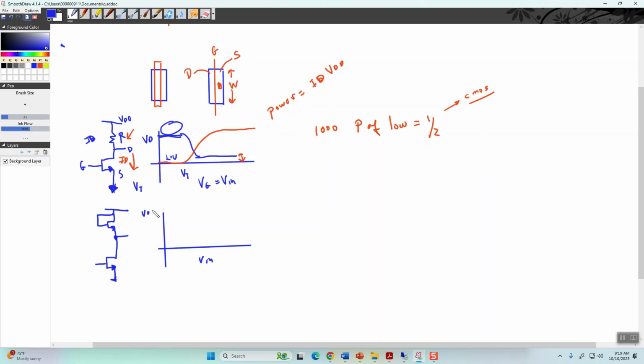Now, what happens is that this can go rail to rail, right? If no current flows, there can be no voltage drop, and so these get connected. Here, however, in order to charge this node to a value, current does need to flow at some point, and since it's diode connected, nothing flows until you're above VT.